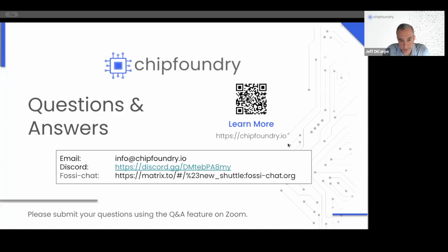Then we run additional data prep, including fill generation, and we add the seal ring around the overall die. Once that's all completed, we run final checks. We expect all those checks to pass if you pass pre-check, but we do run another set of checks to confirm that there are no DRC errors or any other violations in the overall design before we submit to the foundry.